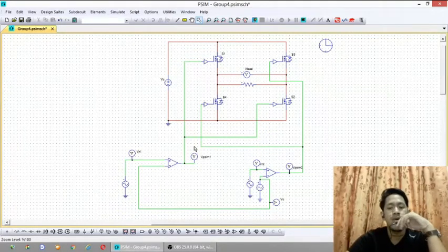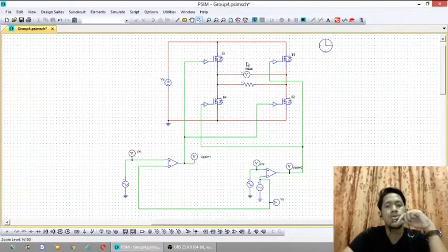VDC. So when we use the unipolar voltage switching, the harmonic content of the output voltage waveform is reduced compared to the bipolar switching. In this unipolar voltage switching also, the amplitude of the significant harmonic and the sideband is much lower for all modulation index, thus making the filtering easier. That's all from me. I will pass to my partner to explain more about our software assignment.